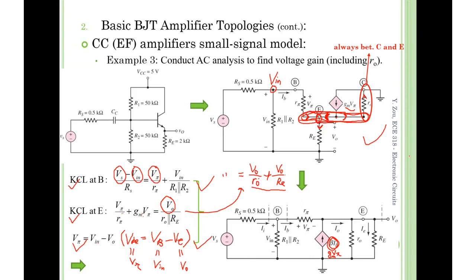But if you end up with four current terms, because you need to consider this guy here as a supernode, you have a supernode involving four branch currents. If you're seeing this, then you're good. You just need to be careful with the voltage polarity. For example, the current flows through R0 upward.